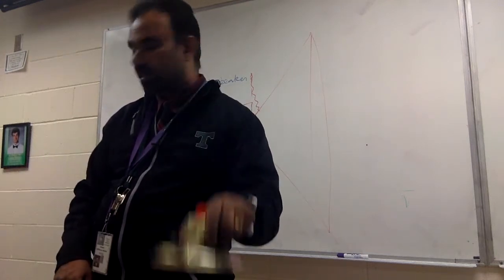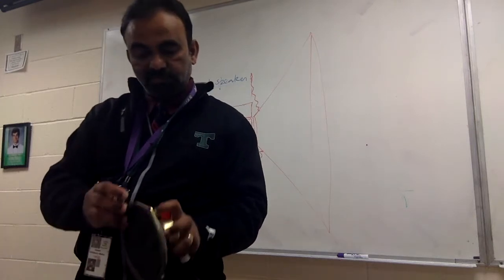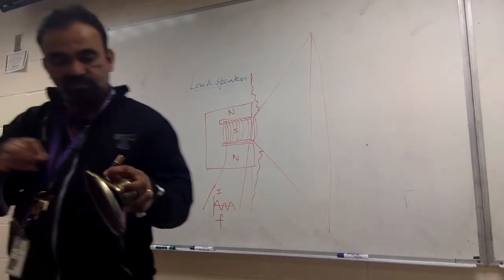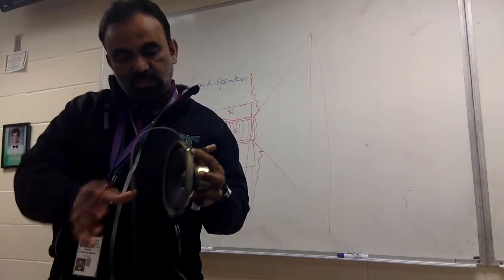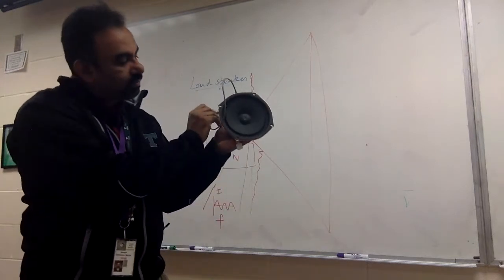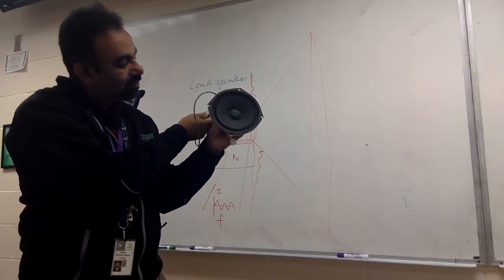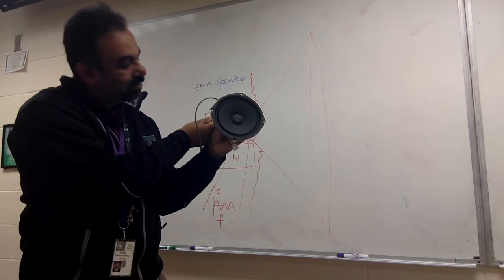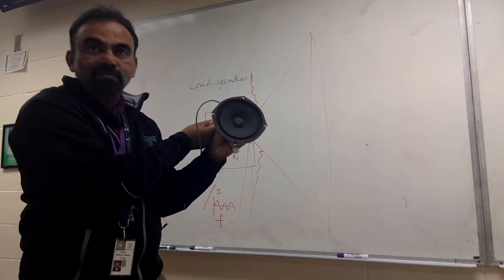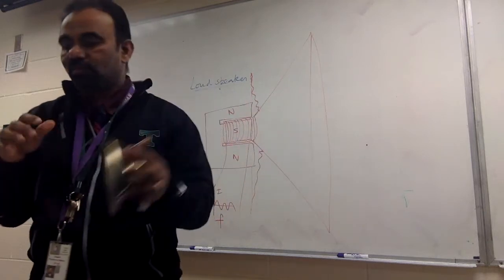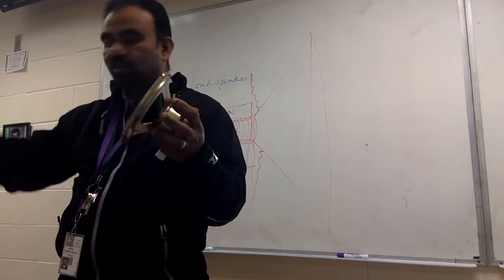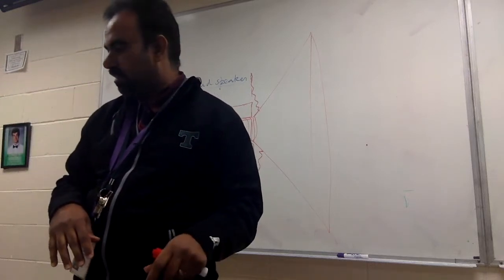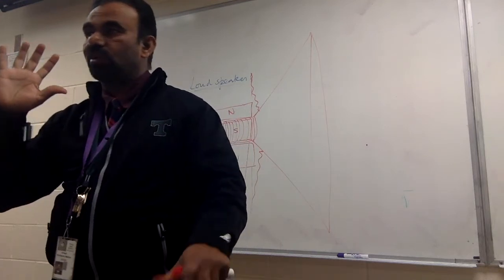If I want to know if this speaker works, I will just connect a battery like that. And you should be able to see the cone move. You see it move? Right? So when I put the voltage, it sends direct current, and that's why you can see the cone is moving one way. Well, these are not good speakers. If they're good speakers, then it should create one knocking sound.